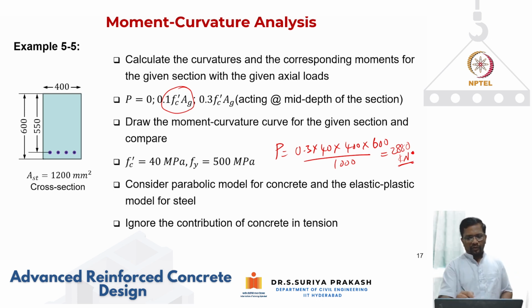Now, we cannot say that if you keep on increasing P, you will get higher moment resistance. In fact, only when the section remains tension controlled does this hold. So that's why we said when you increase up to a certain extent, you will get an increase in moment capacity and an increase in your stiffness. But otherwise, if you put too much compression, then it will fail in compression. It will become a compression controlled failure. Then your moment capacity will not increase. In fact, it will fail in a very brittle mode, which we don't want. So we have to be careful.